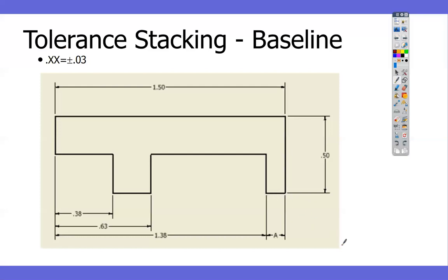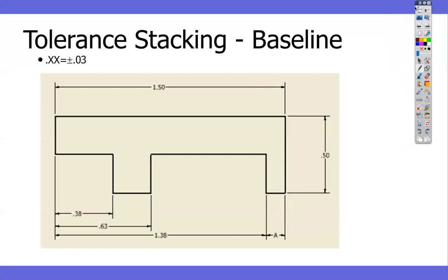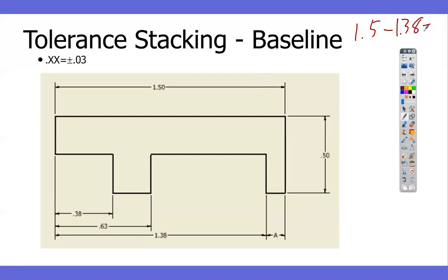How big can A be? How big is A? So let's just do, how big is A right now, not including tolerances? How big is it? 1.5 minus 1.38, 0.12, right? So that's how big it is if everything's made perfect. Things are not made perfect. So it's just got to be whatever it would be.